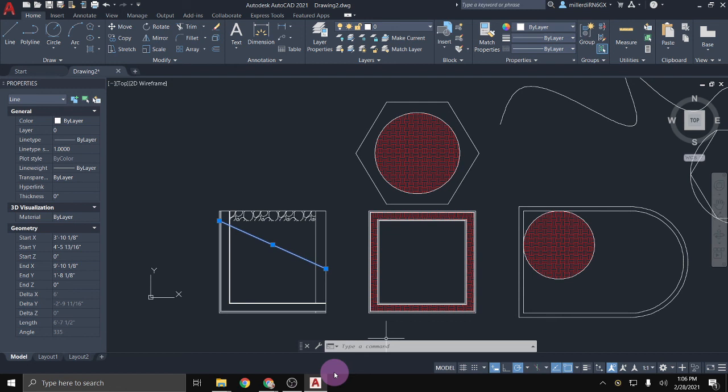So I always recommend doing just your walls as one hatch, just your elevation of one of your views as another hatch, then go into the other elevation and hatch it, then go into the other one, rather than having them all linked as one continuous hatch with all similar patterns in just one go. Because if things do need to get changed, then you have to redo multiple drawings rather than just redo one of them.